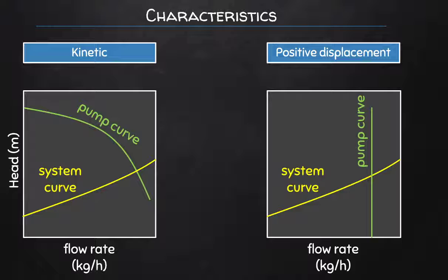The operating pressure is associated with the resulting flow rate according to the system curve from the process in question. The system curve can be shifted to different locations using a control valve or a modification to the process variables. So in other words, the total variable pressure differences.